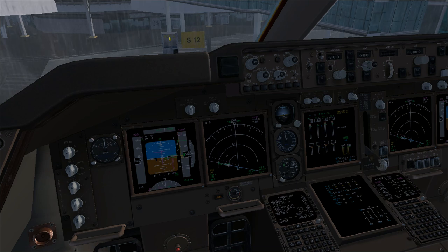Flight instrument, you have to verify indication are correct, and the indication are correct. And you have to check out the flags. The flags can be TCAS off in the ND if the TFG switch is pushed, and it is pushed, and the TCAS is off for now. And also no V-speeds indicated if takeoff V-speeds are not selected. In this case we have selected V-speeds, so we have V1 132. And we have to check out the flight mode annunciator in flight director, blank, toga and toga. This is the standard selection for the takeoff.